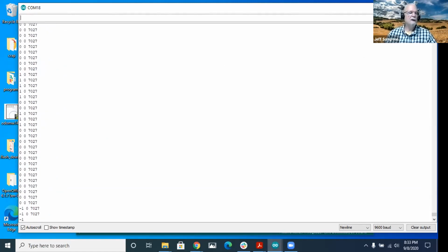So I tried to use the Arduino Timer 1 library, I think they call it. You load that up and you say, create a time base of every 1,000 microseconds, call this interrupt routine. And that was working when I was trying to just use the built-in A to D on the Arduino. But when I try to run it with this thing, it won't. When I try to talk to this board, it just locks up and won't do anything. So I don't know why I can't put this driver code into the interrupt routine. So I was going to try to track that down tonight.